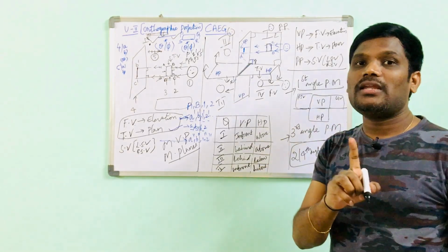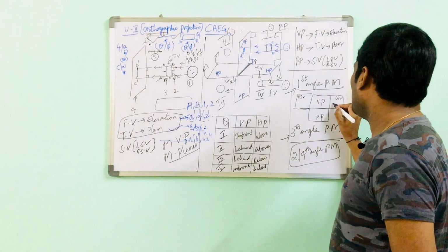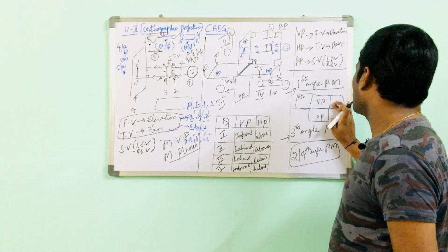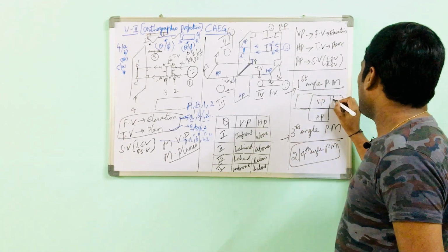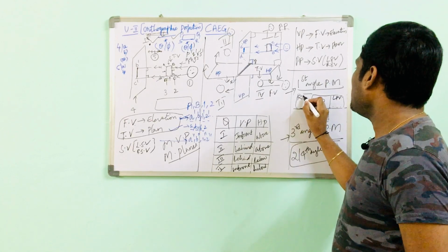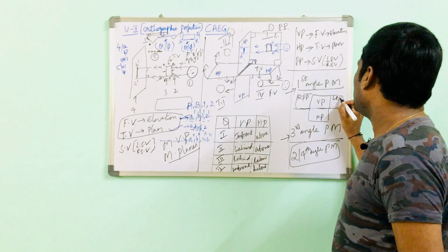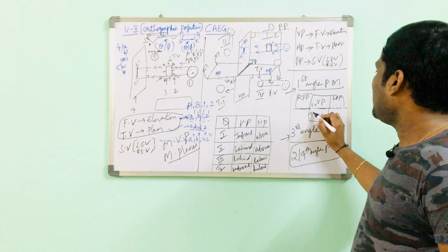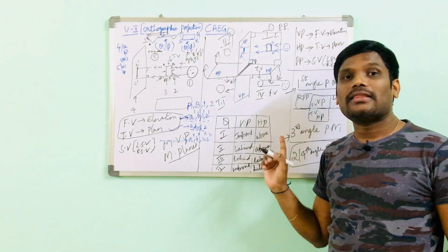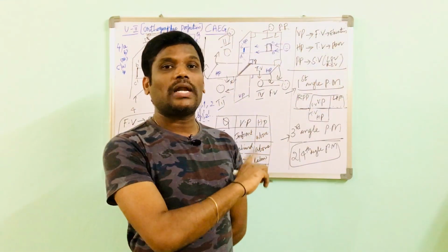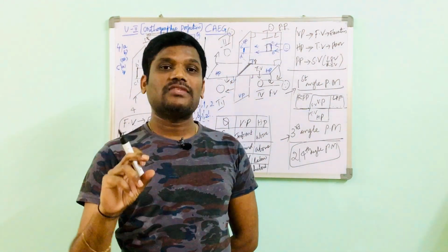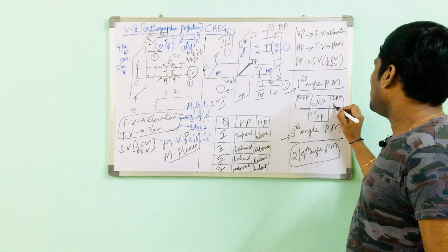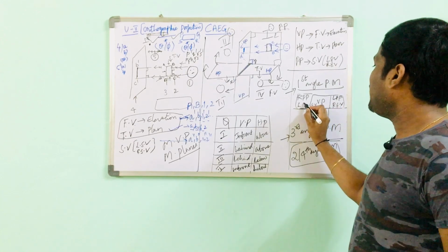The thing to be kept in mind, I'm telling you very fast here, is that for the left side view you get it in the right profile plane, I mean the right side view. For example, let this be the left profile plane and let this be the right profile plane, LPP and RPP. In the vertical plane we see what, dear students? The front view. In the horizontal plane, the top view. If they ask you the first angle and third angle projection method, you are supposed to work out like this. You need to write the theory of it and why it is first angle. You need to work out and draw this, then draw this. In the left profile plane we see the right side view, and in the right profile plane we see the left side view.